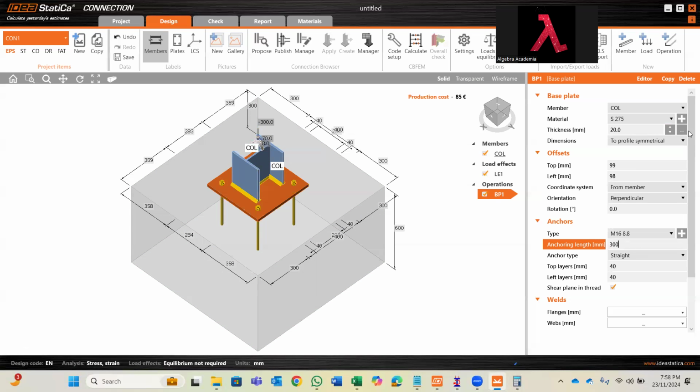At any cost, the distance between the bolts acts as a lever arm, which is resisting the forces. Then the moment divided by this distance gives you the indirect tension. Since I do have tension force, the embedment length should be not less than 200 millimeters. This is also there in the AISC code. 200 millimeters. But now our forces are huge, so I'm not going for 200 millimeters.